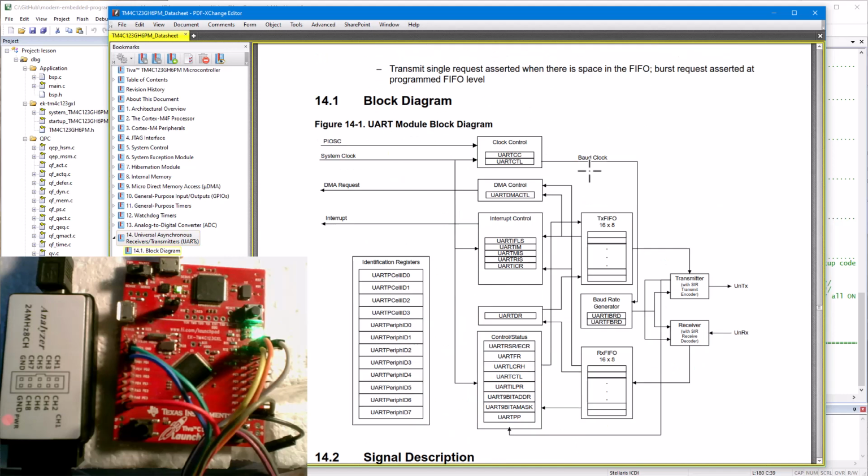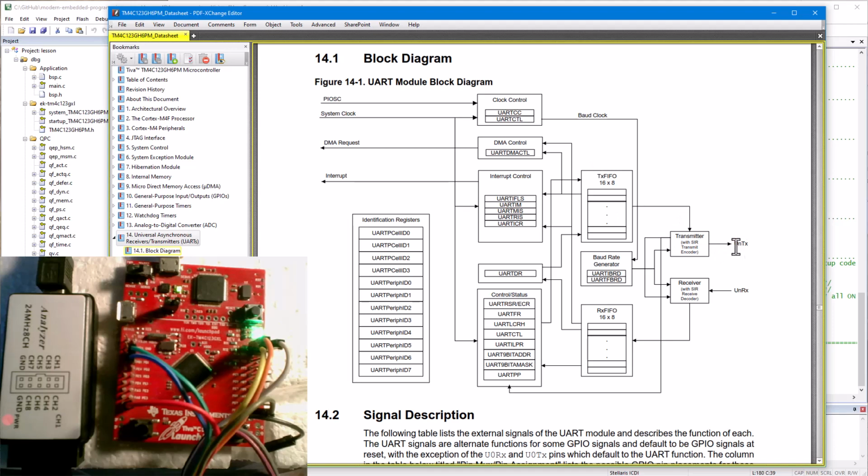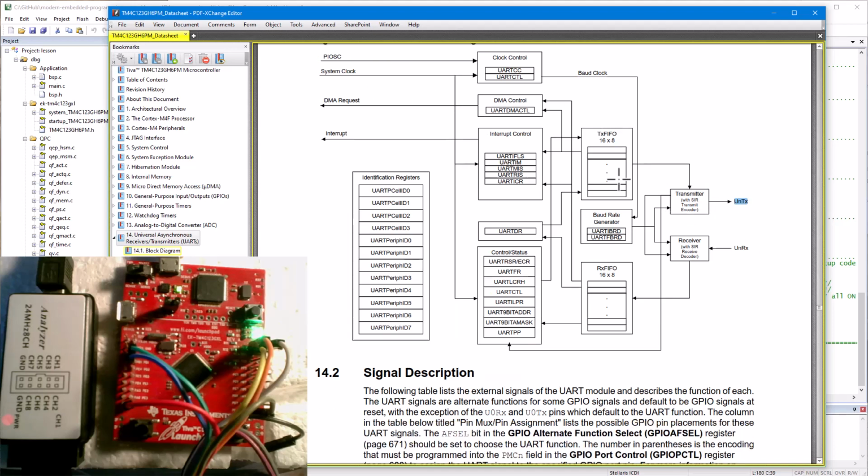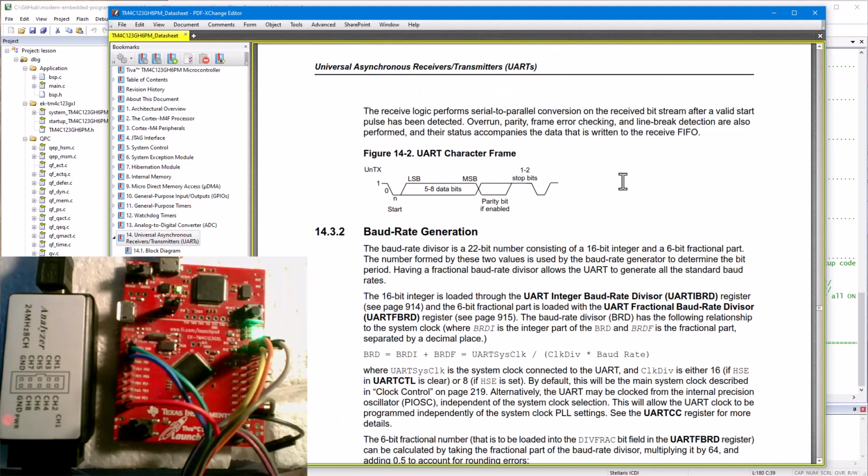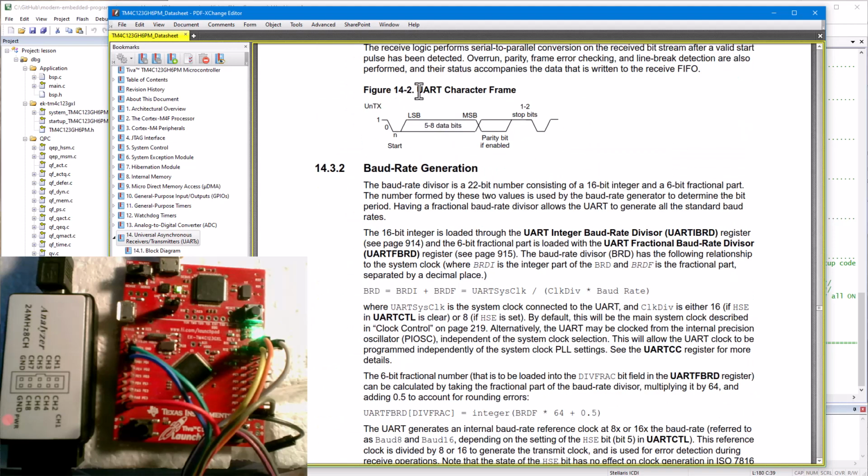I don't want to go into too much detail about how UART works, but it uses just one TX pin to transmit data. The transmission happens by modulating the voltage level on the TX pin. The speed of the transmission, called the baud rate, is determined up front and must match the rate expected by the receiver within 1% or so.